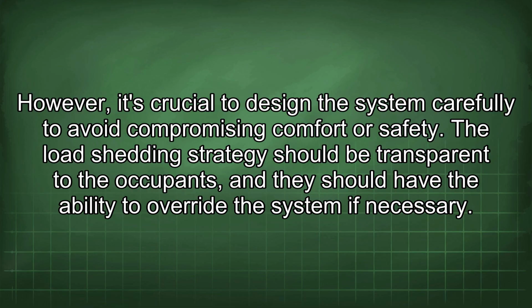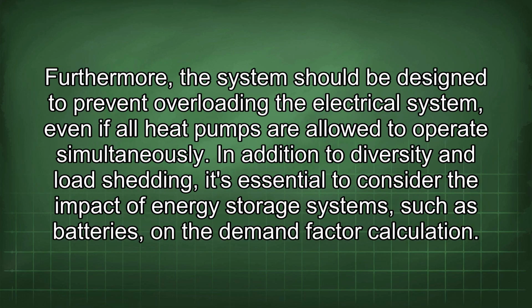The load shedding strategy should be transparent to the occupants, and they should have the ability to override the system if necessary. Furthermore, the system should be designed to prevent overloading the electrical system, even if all heat pumps are allowed to operate simultaneously. In addition to diversity and load shedding, it's essential to consider the impact of energy storage systems such as batteries on the demand factor calculation.